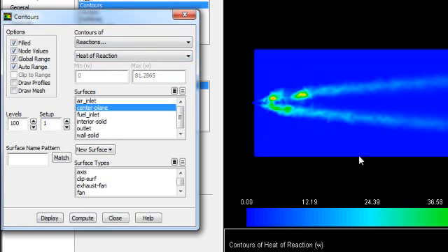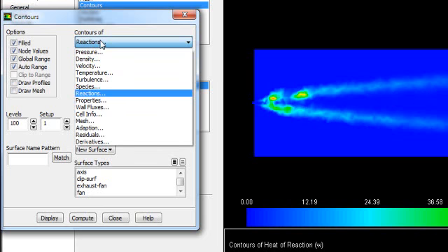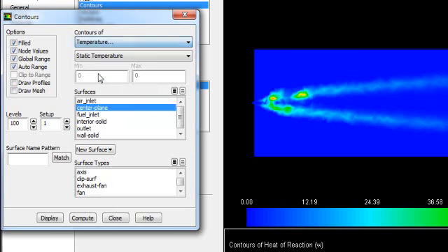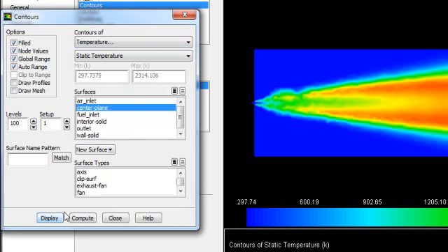So this kind of indicates the flame formed where the maximum heat has been generated. So this is the flamelet model, and you can see the trace of the flame also. So with these options you can see lots of different parameters and different features of combustion. You can also model NOx emission. You can model different types of air fuel mixture.